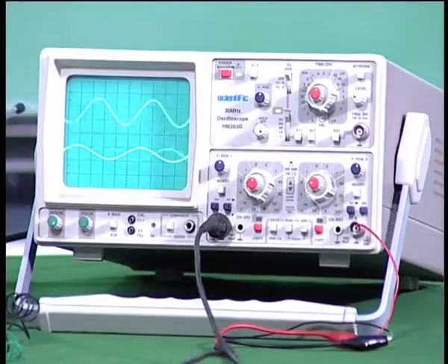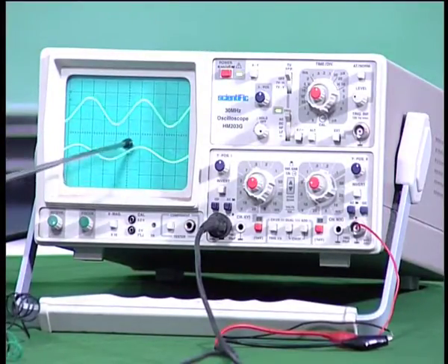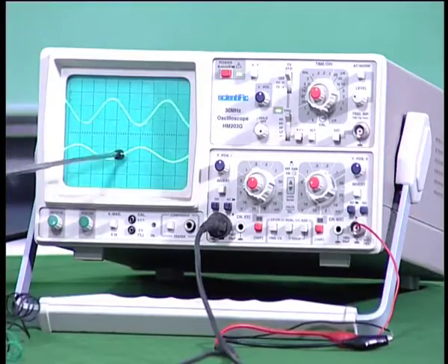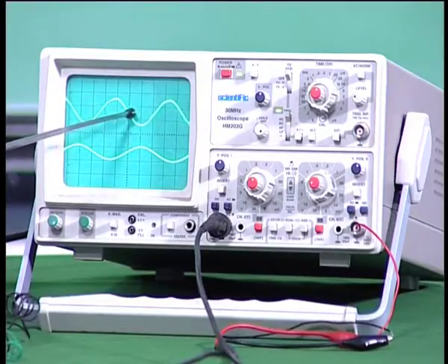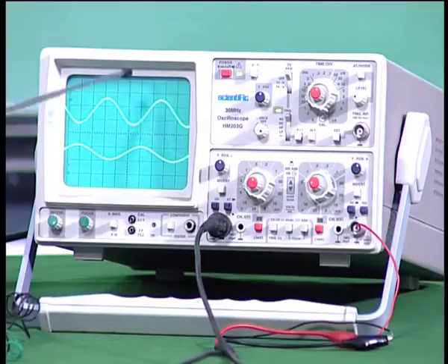So, now if I change the frequency in the oscilloscope, you can see the 2 signals are seen. This steady one is due to the oscillator that we have constructed. This one is from the standard oscillator that I have used. So, now what I am trying to do is superpose them and measure the frequency.